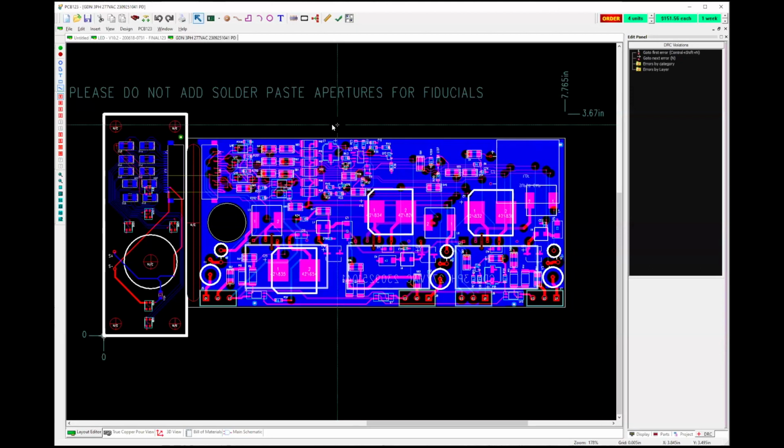But if you don't know those rules and you just want parts to use on your board, you can order those from Snap EDA, which is an online library service. A lot of times they'll have the part already in the library, and if that's the case, the part will be free. If you don't find the part you're looking for in Snap EDA, you can just order a part, and there's a little fee for that.